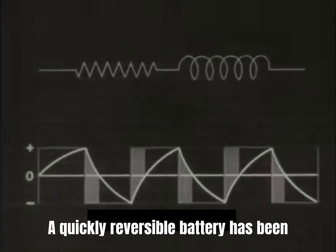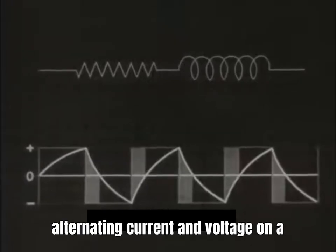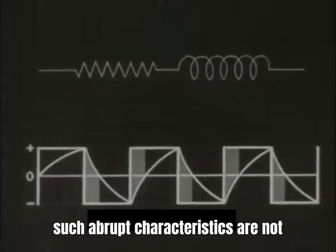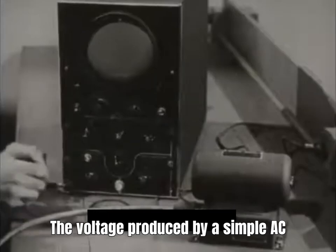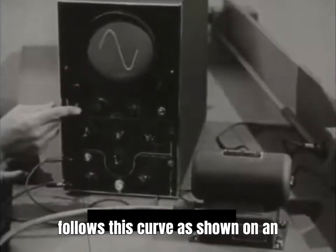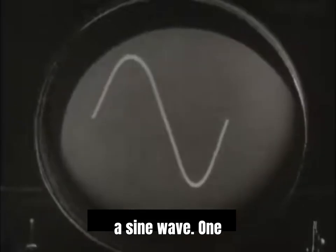A quickly reversible battery has been used to illustrate the generating of an alternating current and voltage. On a graph, this produces a square-shaped wave. Waves of such abrupt characteristics are not common. The voltage produced by a simple AC generator or a vacuum tube oscillator follows this curve, as shown on an oscilloscope. It's called a sine wave.